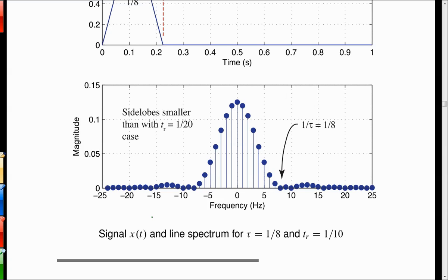So that's true, and actually pulse shaping is used in all kinds of communications. It's used in cellular telephony to make sure that your neighboring signal, with Fourier transform theory, you could have another spectrum sitting in here. The very first simulation project, you're going to be doing some things like that, playing around with moving adjacent channels together, and I'll have you send some discretized audio signals through, and you'll be listening for the interference that can be created if you try to pack things too closely in the spectral domain, and how that impacts the quality of the speech that comes out.